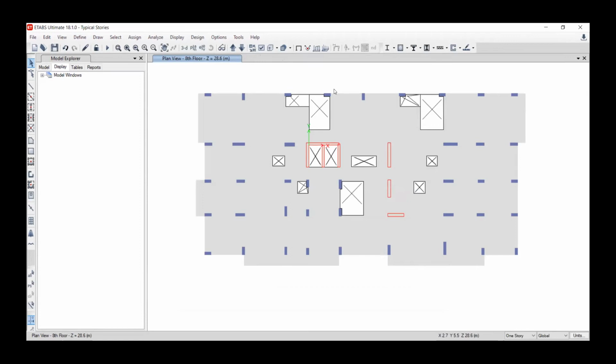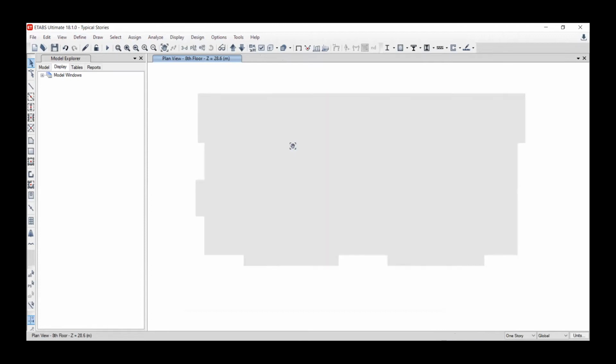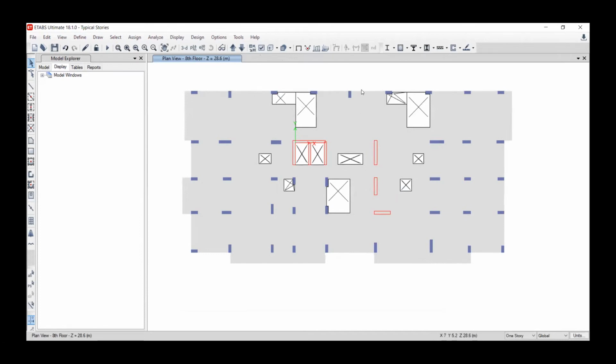The slab here is not inserted from the architect engineer. You should use the thickness of the slab. How to know the thickness of the slab? You need to know the largest span in the two-way system. We consider this as a two-way system. The largest span is divided by a value based on the code. So if we go to the code, I have a screenshot of this one.